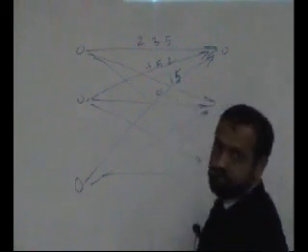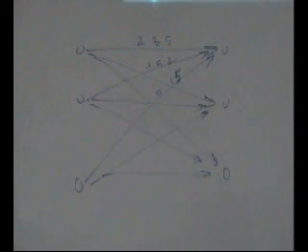So it is a very interesting and current area of research to estimate not a channel but a matrix of channels. It has 9 entries, and every entry is a channel. Within every entry, if there are 3 paths, you need to figure out 3 coefficients. If there are 5 paths, you need to figure out 5 coefficients.